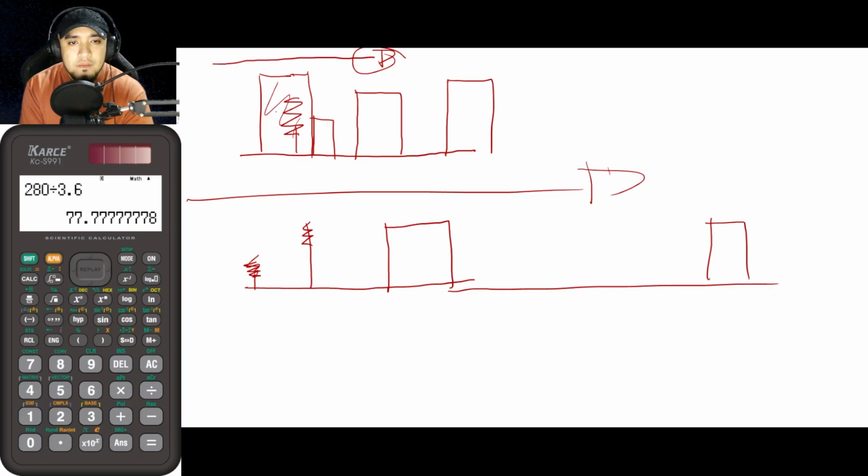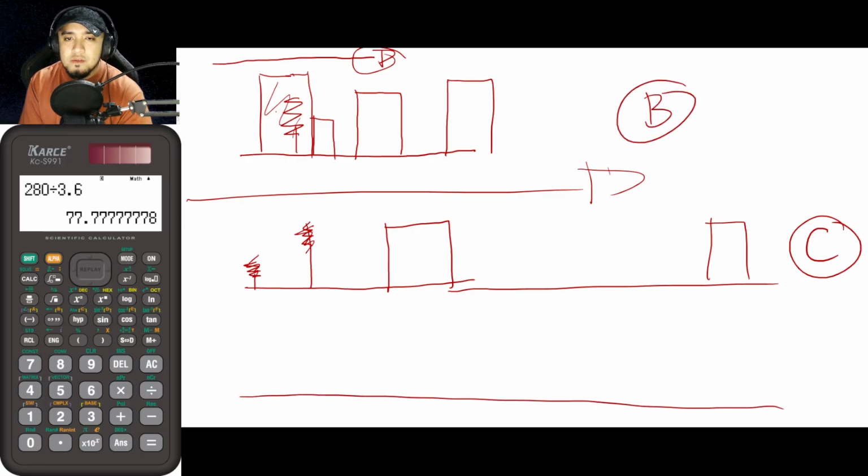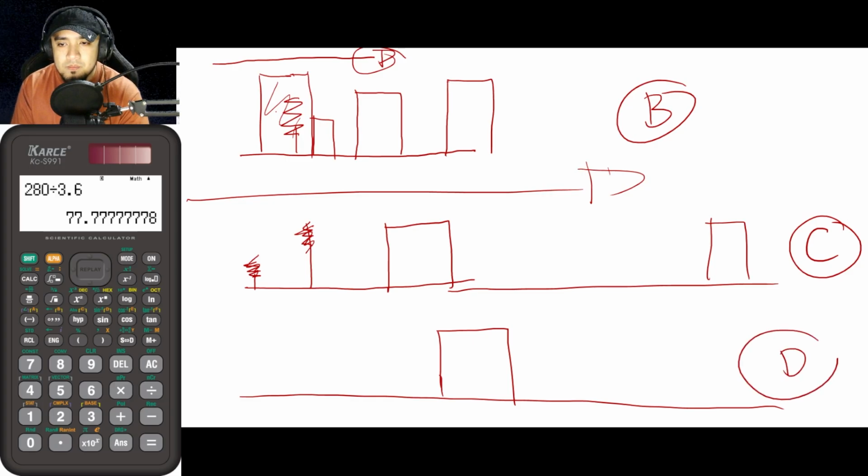It might have undergone some obstructions, but only a few, and they are scattered. So from that, guys, this is now C. Surface roughness C. This is surface roughness B. And for surface roughness D, unobstructed. For example, you bought an island, it's all yours. You bought a desert, it's also all yours. From that, surface roughness D.